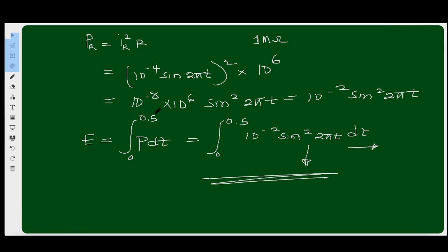Number 1, for an ideal capacitor, there is no current through the capacitor if the voltage across it is not changing with time. If the voltage is constant, there is no current through it. So basically, I is equal to what? We said I is equal to C dV/dt. If the voltage is constant, what do we have? C d/dt of a constant. Let me call it K because we already have C here. And when we differentiate the constant, what do we have? We have 0, which means that I will be equal to 0.